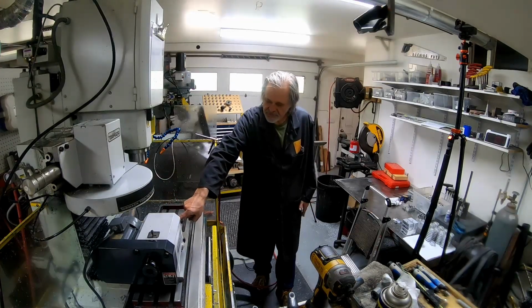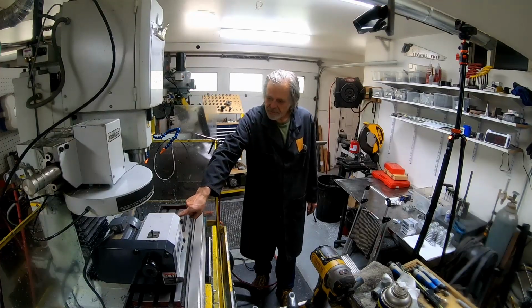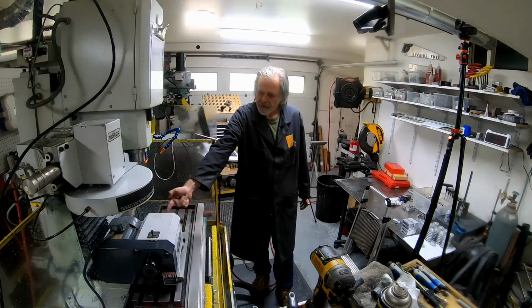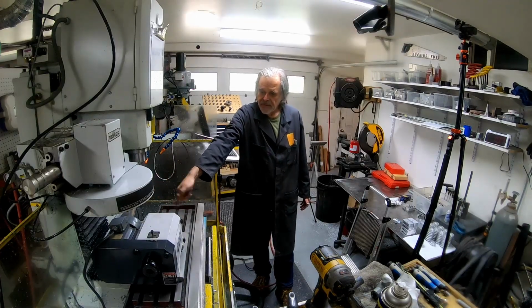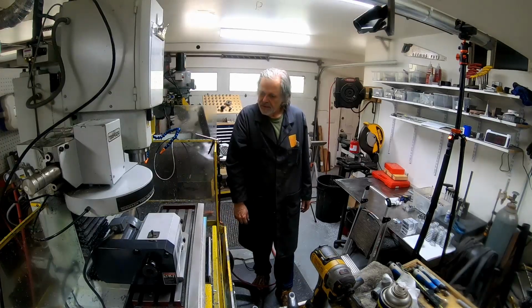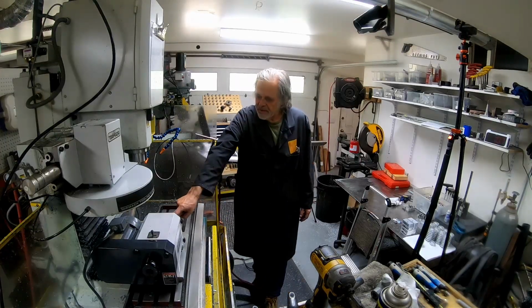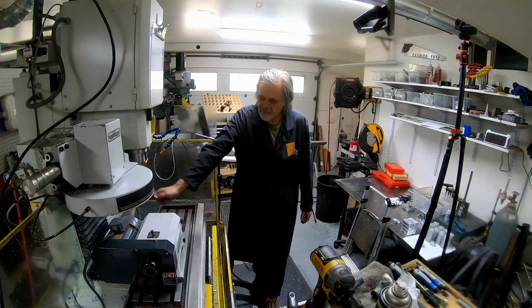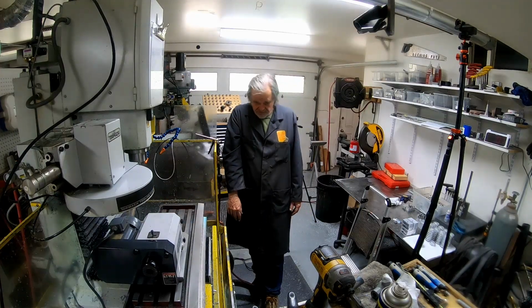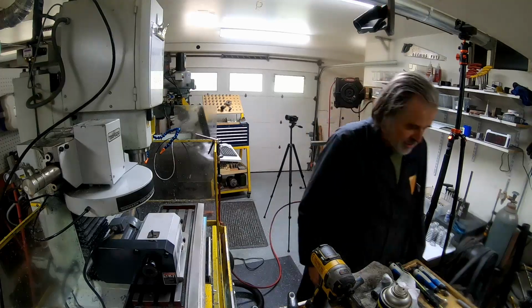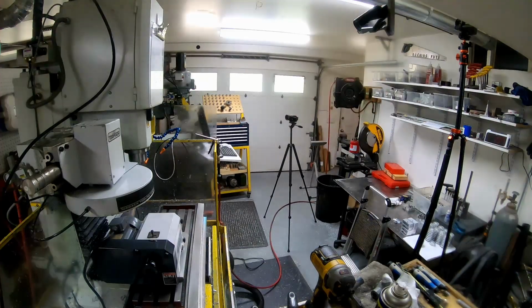mounting from the front, as you would imagine in a normal manual lathe. The tool actually comes in from the top and the spindle rotates the opposite direction from the direction you would expect for a manual lathe. So the height of the center line of the tool is set using the y-axis. Very confusing, a lot to remember, many, many, many opportunities to make mistakes.